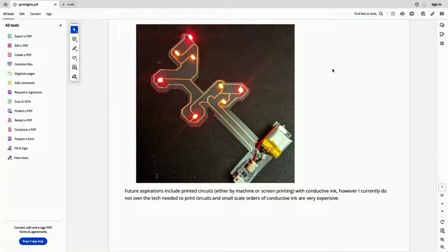Then we had to talk about flexible circuits. I didn't have a lot of funds to do this. It's probably a relatable problem for most people trying to prototype things. So what I did is I got transparency sheets, and then I got copper traces, and I cut them out myself using a Silhouette cutter. You probably could use a Cricut as well. I used a Silhouette, and I can tell you right now, buy extra blades if you're going to do that, because the copper tape is going to wear it down super fast, and you're going to have to go a little bit thicker than you want on your traces. It can't get super fine.